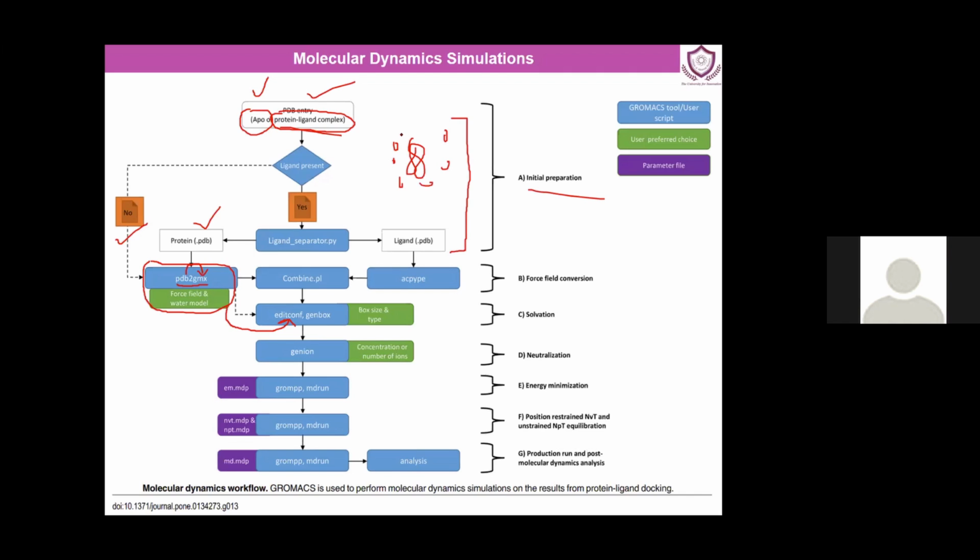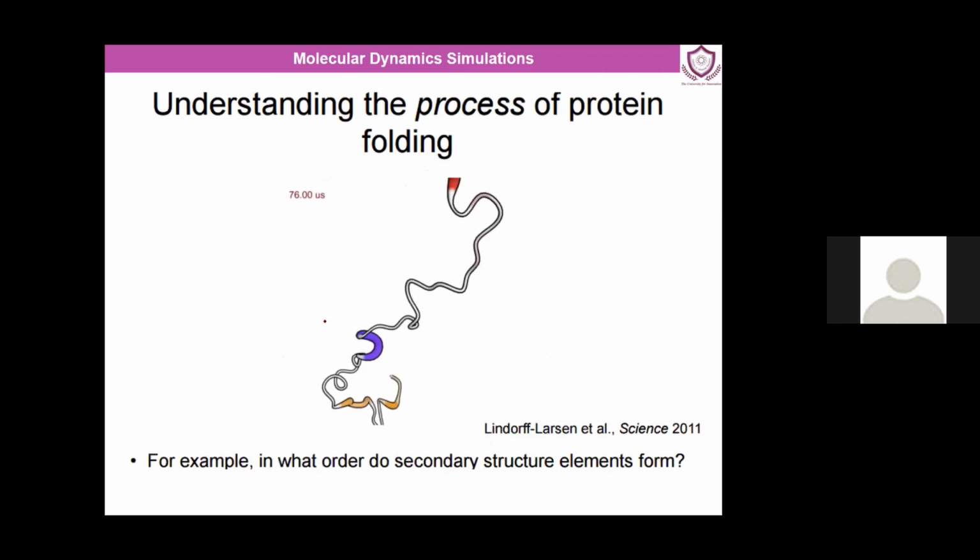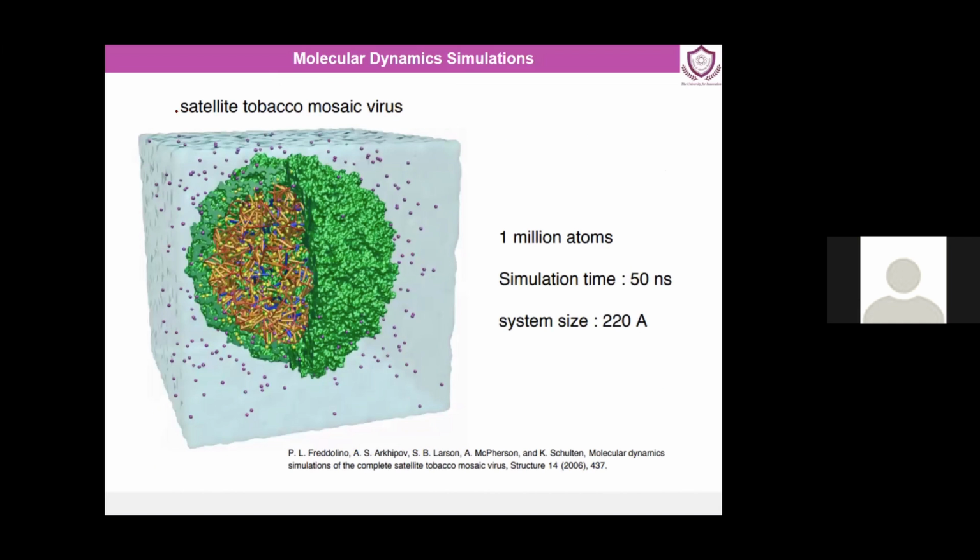You cannot just put a water molecule like this. You need to first create a kind of a 3D box and then add a solvent molecule into it. So this configuration of box is defined by this program editconf. So it will look something like this. So when you prepare this, it will look something like this.